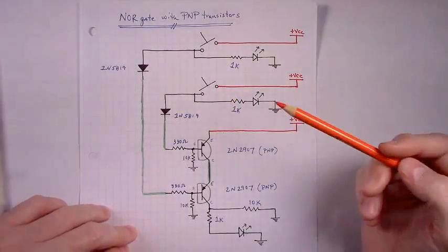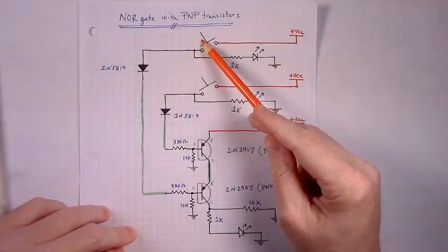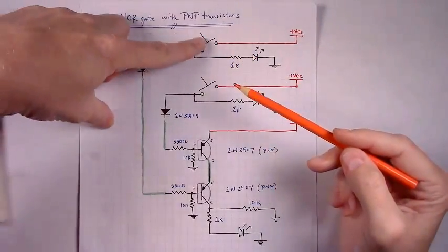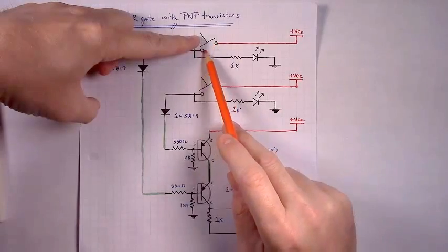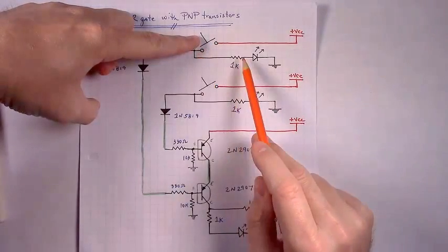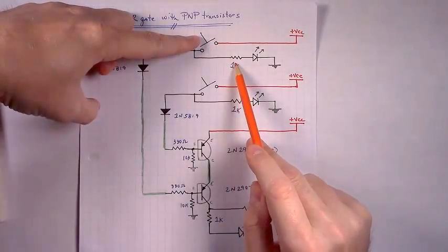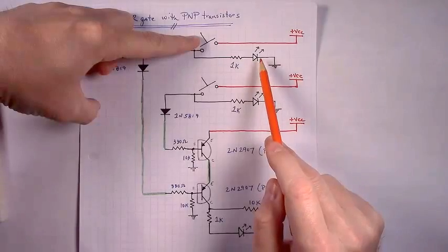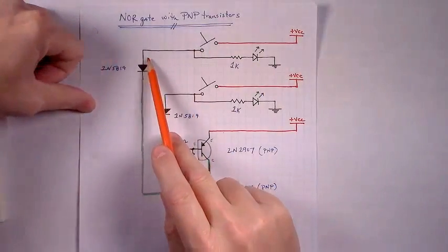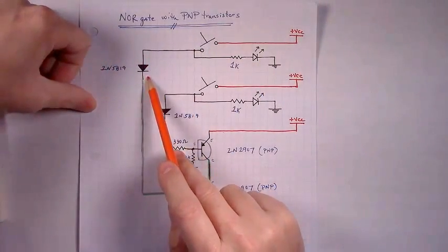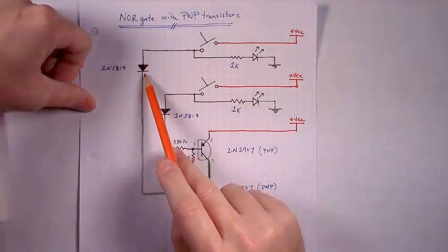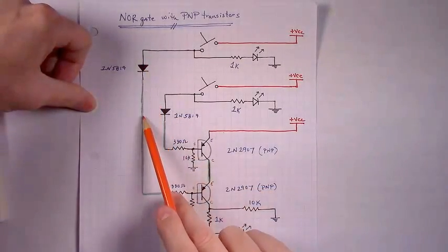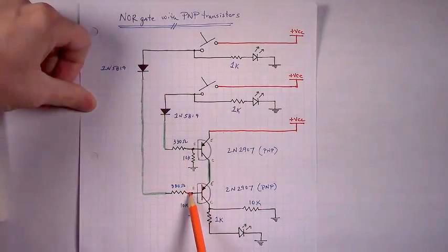Well, what happens when we do press a momentary button? When we push, say, this button down, now we have VCC traveling across the contacts of the momentary button. Some will go through the 1K, lighting up the indicator LED. The rest will cross the Schottky style diode. All it takes is 0.3 to 0.4 volts to force the Schottky to conduct, pushing it down to the base of